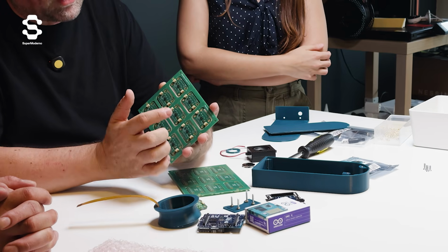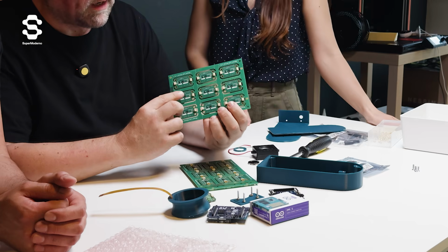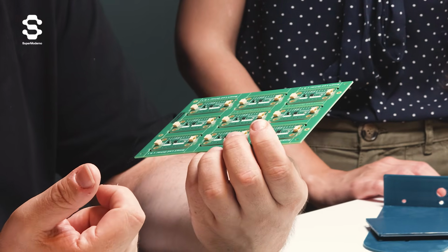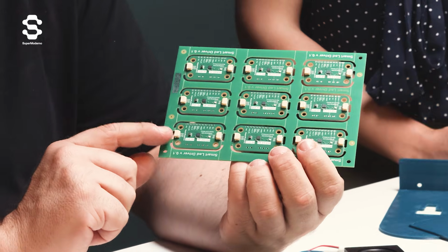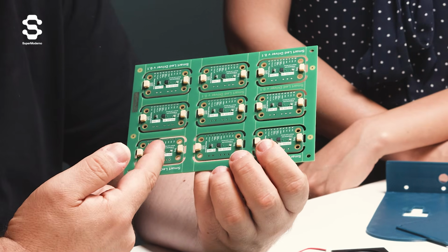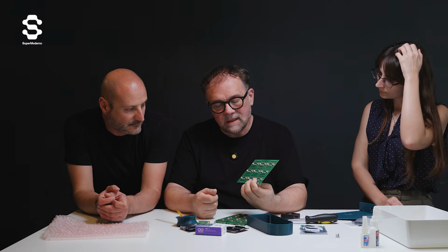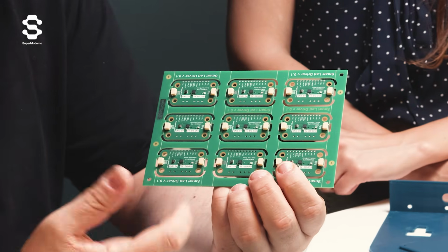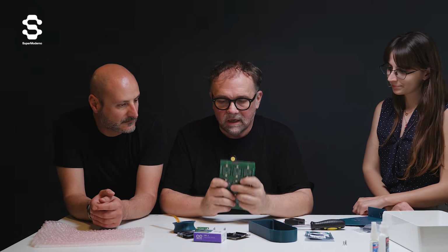And it's got a microphone on it. And you can actually use I2C to control different parameters on the speaker, like volume, for example. And the last one, I think it's very universal. It's a small microcontroller that's designed to drive smart LEDs, like what Adafruit calls NeoPixels. So the idea is you have a Modulino I2C connection, the microcontroller here has a firmware, and the firmware drives the LED strip without having to implement it in the firmware on the board. So this is going to be useful for a bunch of different applications. That's why we made Modulino, so we can reuse them in other projects.